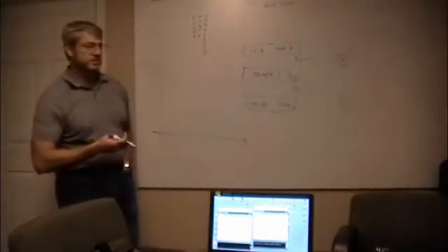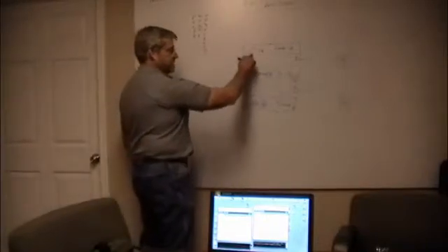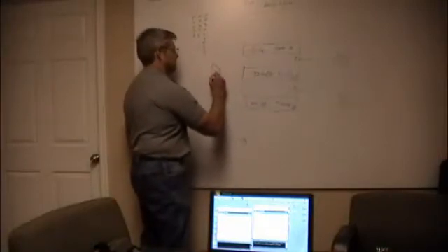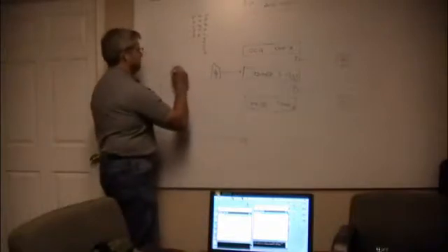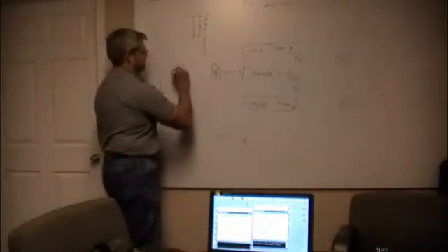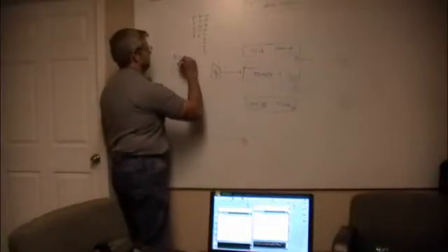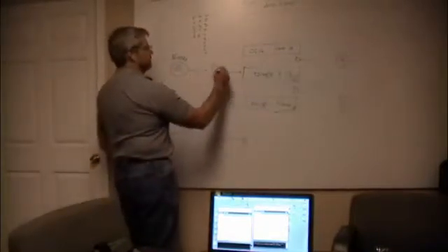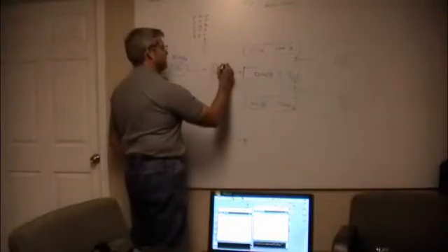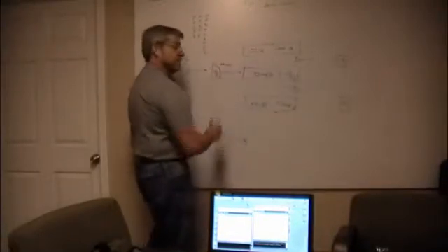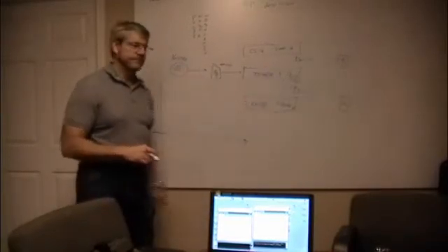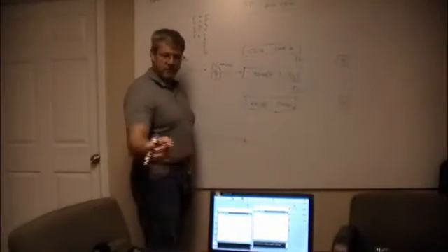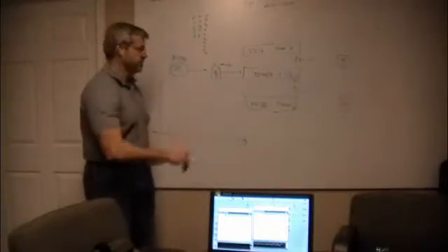One of the modes you can do is, anytime this count matches that count, so there's a prescaler and there's a system clock out here. I'll draw it this way. System clock, 16 megahertz on an Uno. And the prescaler has a series of dividers in it. Your choices are basically no clock, so turn it off. That's great to save power, because if this thing's sitting here running, it's using power. When you're doing micro power type stuff where you want things to go to sleep and use nothing and run off of one little coin cell for a month, you need to shut down everything you can.